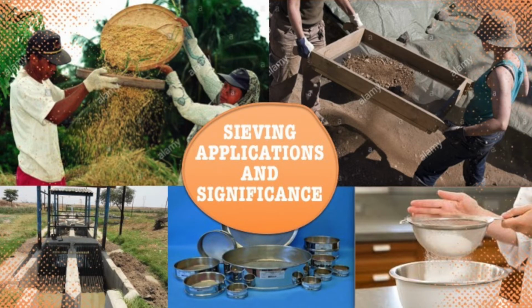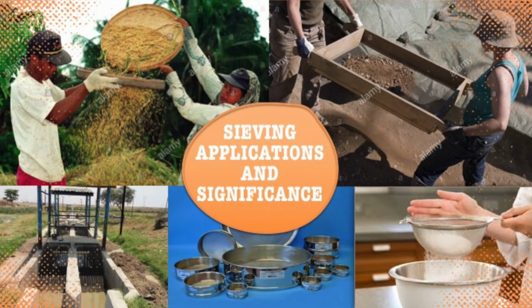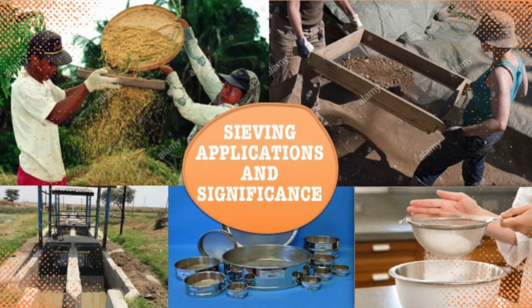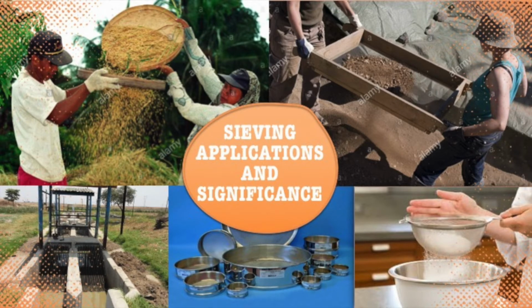These predetermine the process of application. In safety screening, it facilitates the correct quality of pharmaceutical products by removing contaminants like pieces of packaging and personal protective equipment. Grading, on the other hand, sorts different sized powdered particles in preparation for further processing into tablets. So that's it for the applications and significance of sieving in the industry.